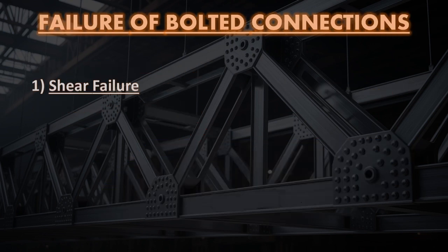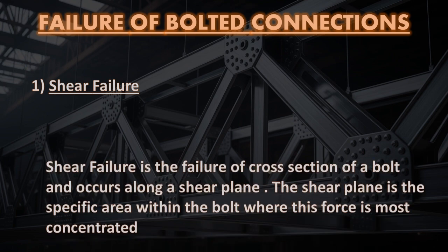Failure of bolted connections. 1. Shear failure. Shear failure is the failure of cross-section of a bolt and occurs along a shear plane. The shear plane is the specific area within the bolt where this force is most concentrated.